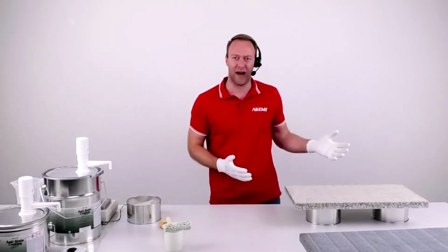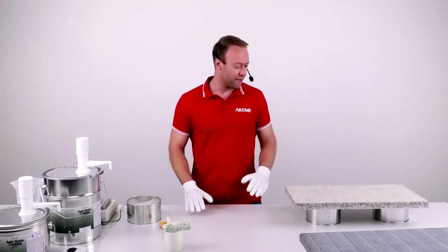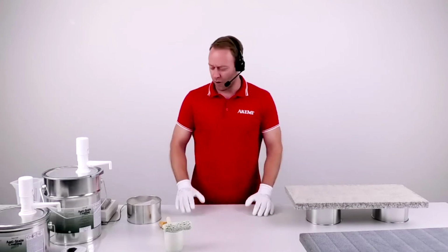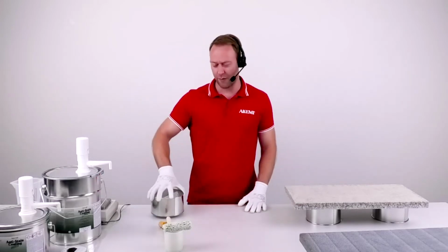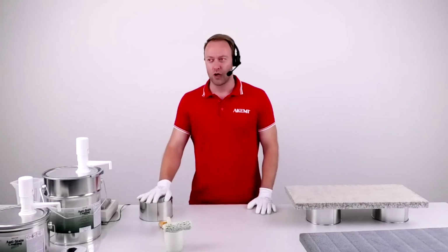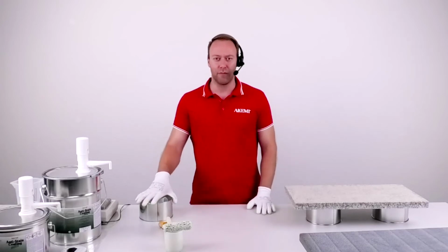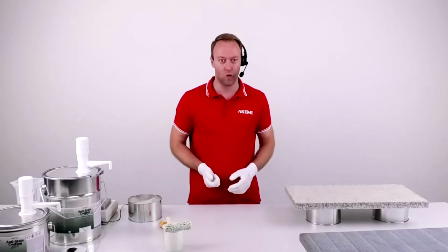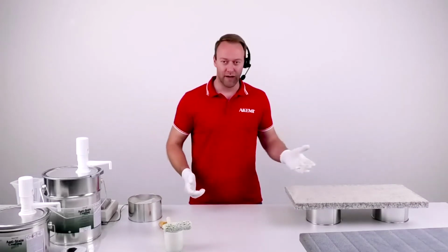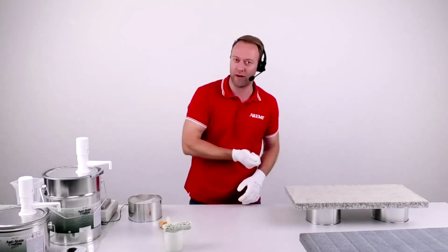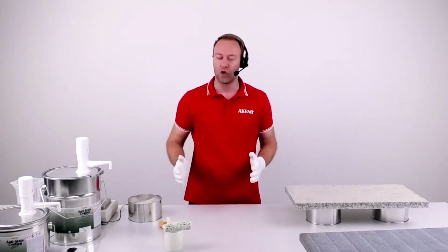You have to work a little bit faster, but you also don't have to do a sprint race, because we have some good working time. We say 30 minutes roughly at 20 degrees. So you can calculate 15 minutes at 30 degrees, 7-8 minutes at 40 degrees. You have time to spread a mixed solution. So I think 8 minutes, when you mix, I don't know, 1 liter and you put it on different stones and one other guy is starting rolling, usually there's no problem.